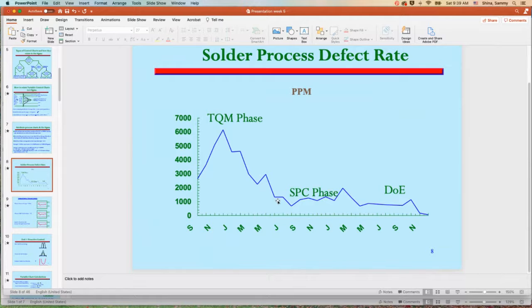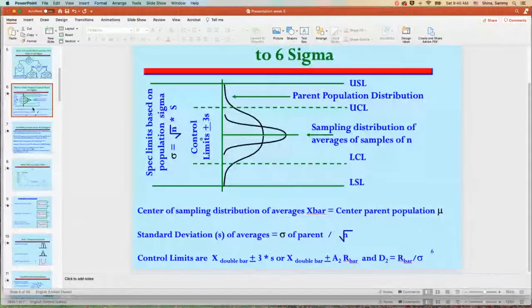So to put these tools in perspective and to tell you that the most important thing is control charts are distribution of sample averages. Even if the population is not normal, the distribution of sample averages is normal. And control charts and reject rates, the connection is process capability, CP and CPK. So these are the 3 pieces we want to connect together. Okay, so that's the high level.